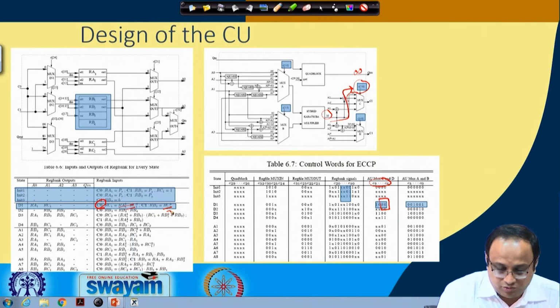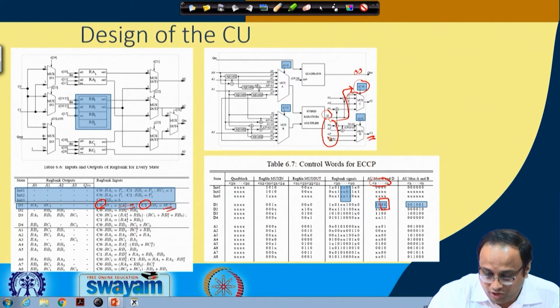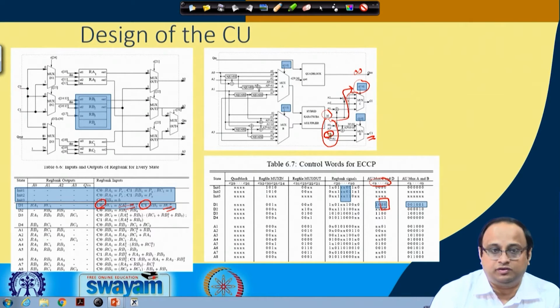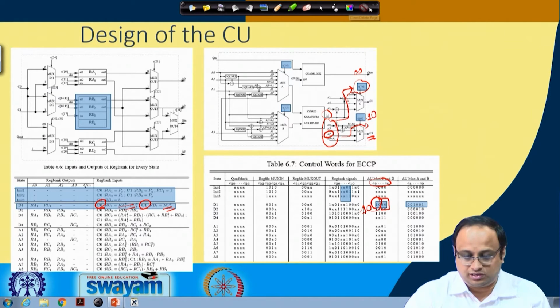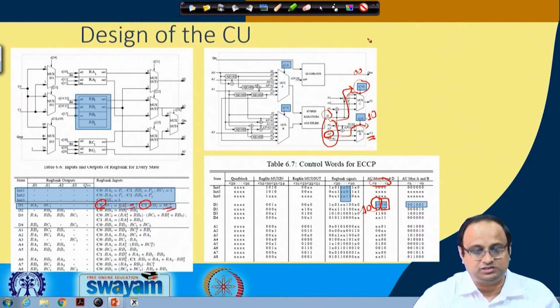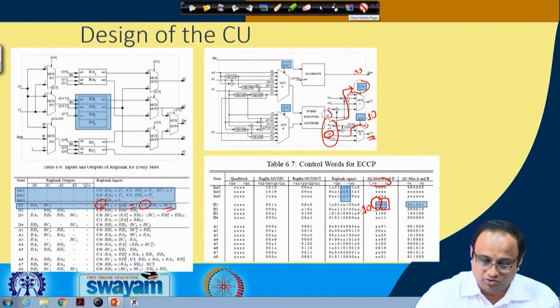The other output is RC1 to the power of 4, which you need to pass to C1, that is this bus. If you see the inputs here, out of them, A1 to the power of 4 is the input I need, and therefore I need to pass this out as an output. So this line needs to be made 1 0, and that is essentially done by this control where you make it 1 and 0. This explains how you set the control so that you configure the circuit. All the remaining steps are done in a similar fashion, which I leave to you as an exercise. You can verify each of these steps and try to understand their correlations.